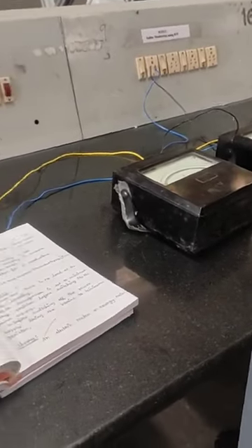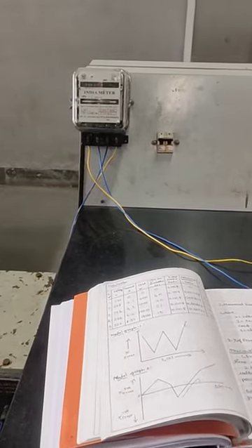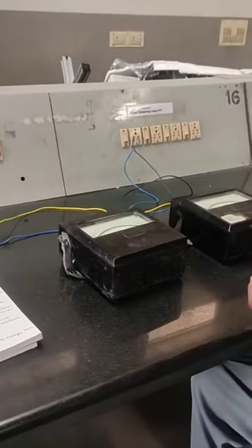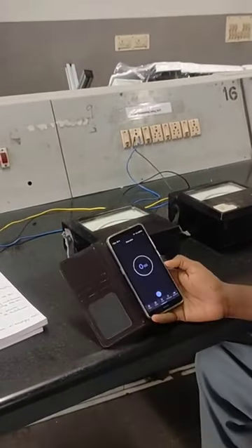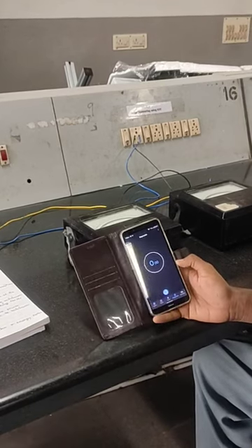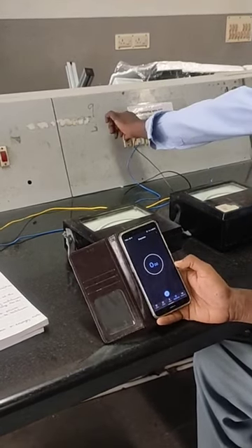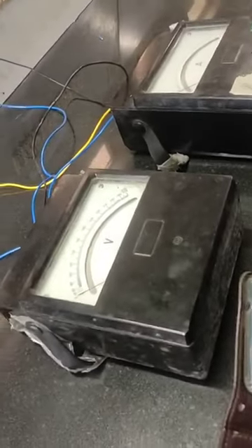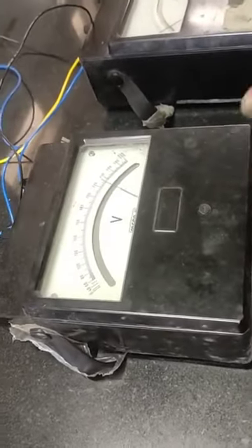So let us start our experiment now. As usual procedure, switch on the supply. Initially I am giving zero load. All the times I am using 3 revolutions. The revolutions can be noted down with respect to the stopwatch. Here we have a stopwatch, voltmeter and ammeter. Initially we have zero revolution. Now if you switch on the MCB, the voltmeter will reflect.